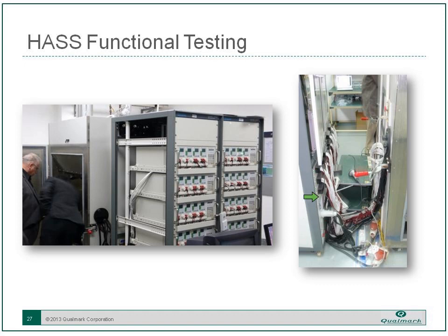So now you are using the lessons learned from HALT, and HALT really gives you a good opportunity to wring out your functional testing and see what does and doesn't work, what you should be monitoring, what kind of failures you see. If you're getting error messages that are meaningless, you need to get rid of those before you get into production so that there's no interpretation that needs to go on by the operator. And you've also had a chance to learn about those key performance indicators so you know what other parameters you're looking for as you get into your functional testing.